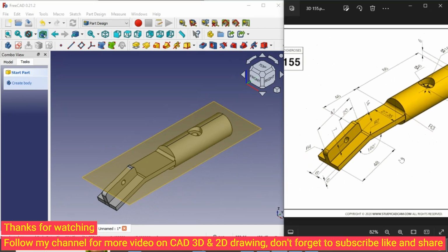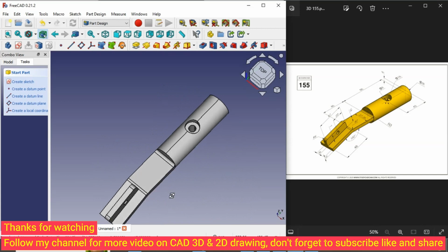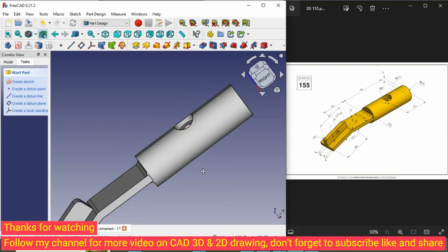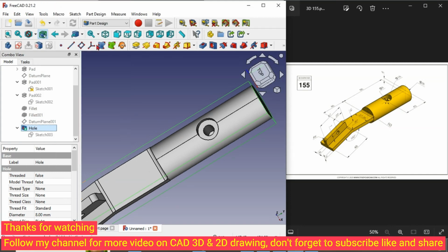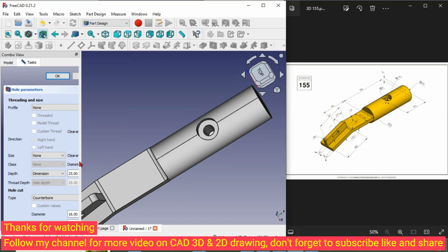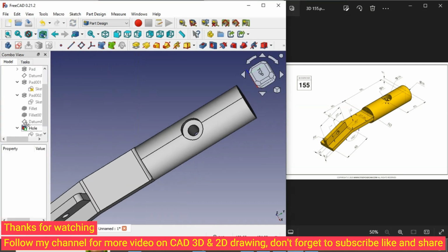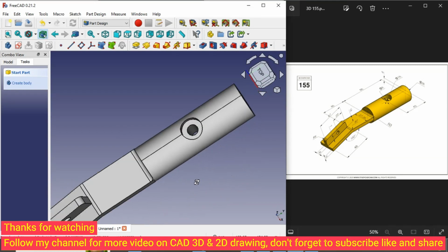Okay, check back with the drawing. Click on this datum, click spacebar to hide the datum. So I think our drawing is done. Yeah, but okay, it doesn't go through. Click back on the model. We need to change the hole setting. Click hole, edit the hole. So this clearing here, the depth will be to all. Okay, that's okay. Now see, the hole goes through the cylinder.